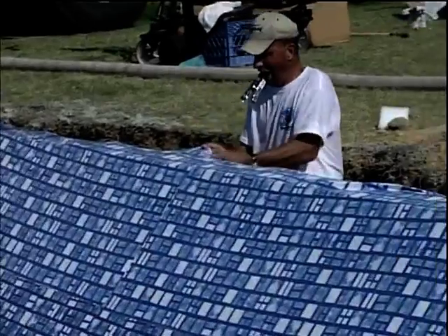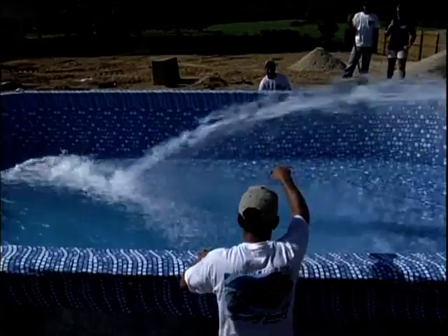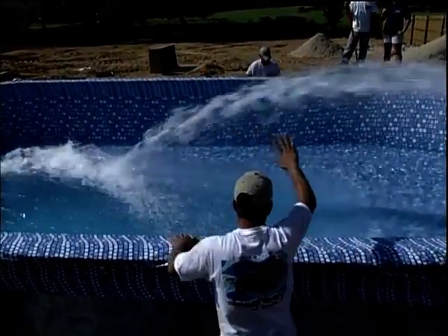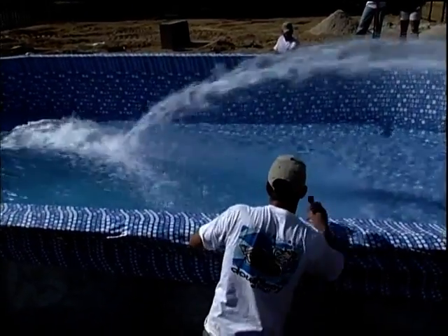You may start filling the pool with water, but be careful to keep a watch on this process. At certain points, you will start to release the liner and allow it to stretch evenly. This is very important when you have a pattern liner, because if the liner does not stretch evenly, you will see a distortion in the pattern.